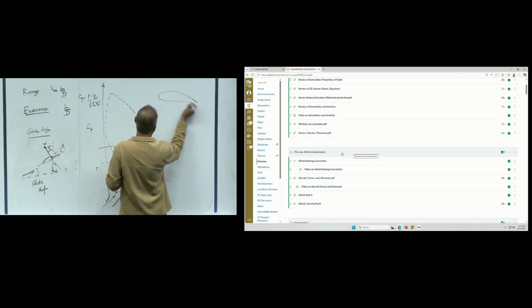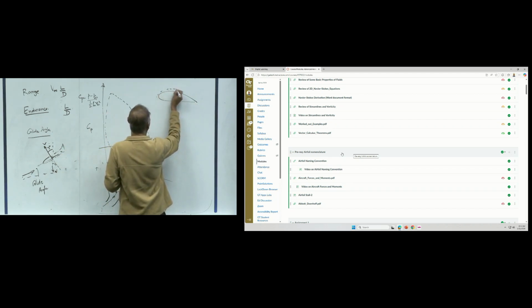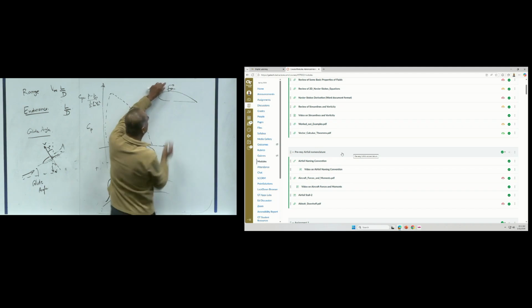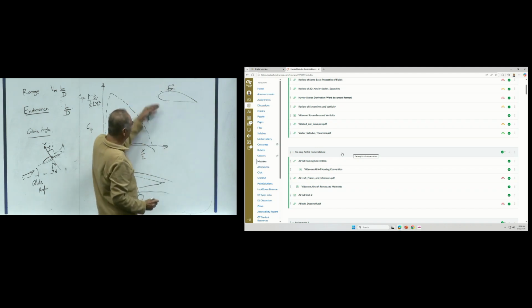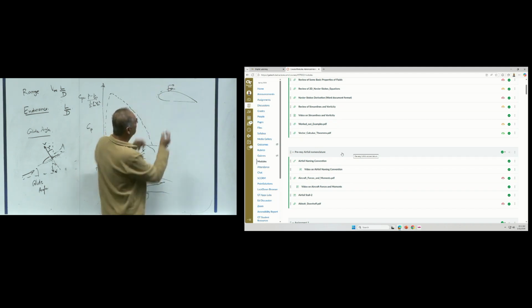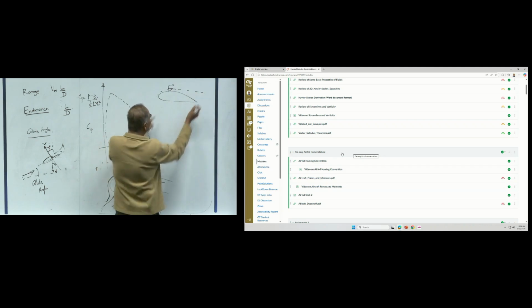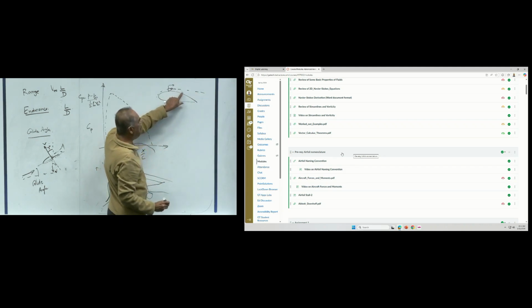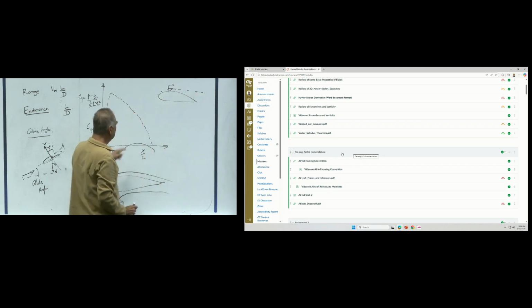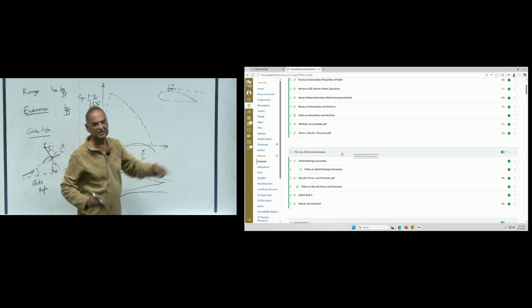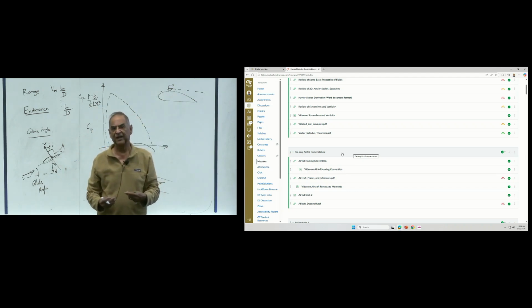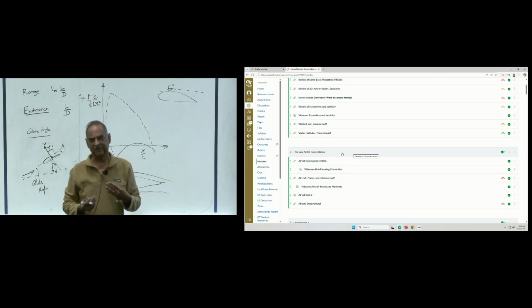The boundary layer on the airfoil will look like this. It's a velocity profile like this. This is the outer flow. This is the boundary layer. These molecules moving through this boundary layer are being slowed down by two effects. One is the wall, skin friction, is slowing you down, and the adverse pressure gradient is slowing you down.